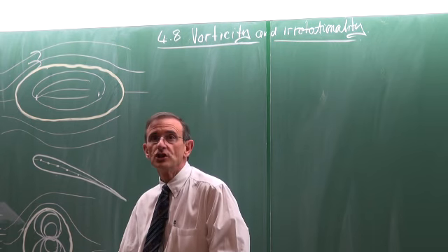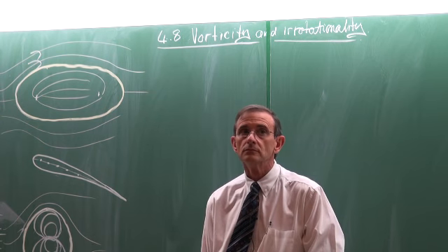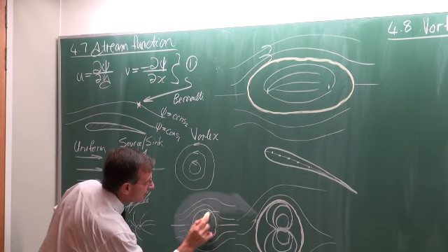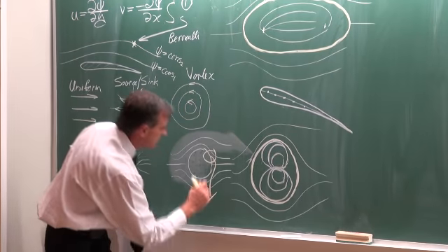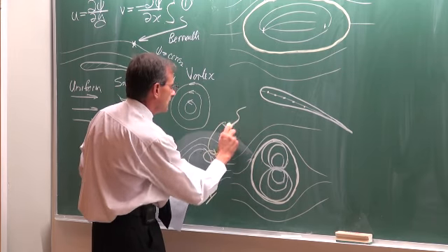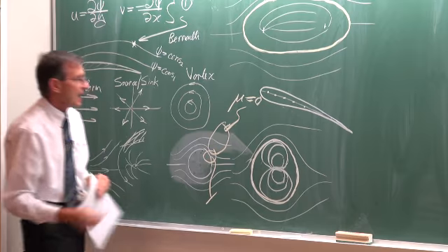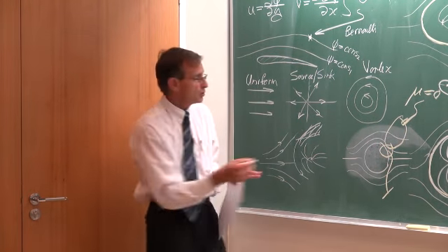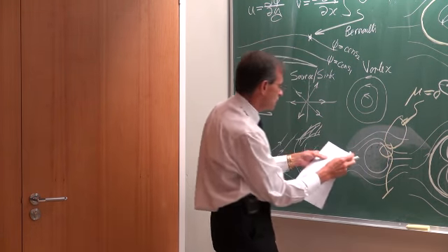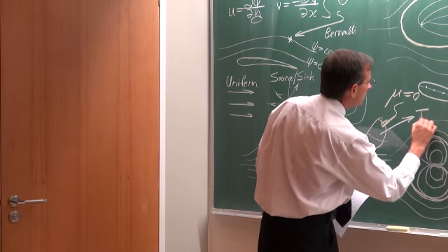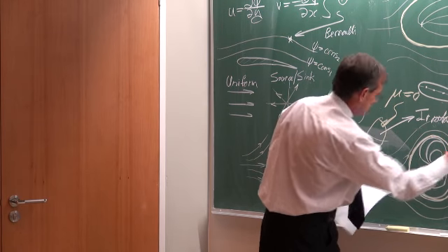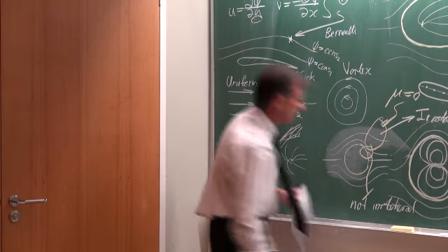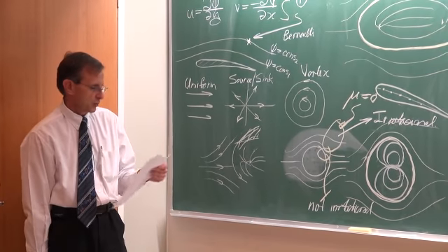Right, in terms of these bodies, ladies and gentlemen. Okay, so what was now very important with all these bodies is to realize, as I've said, that in this area here, or this area here, outside the boundary layer, we can make the assumption that the viscosity is equal to 0, and it will be a very good assumption. Very close to the boundary, that starts becoming very important because we need the boundary layer there. And just to distinguish it, this would be called irrotational flow. Okay. And this would be not irrotational flow. Close to the boundary, it is not irrotational, and away from the boundary would be irrotational flow.